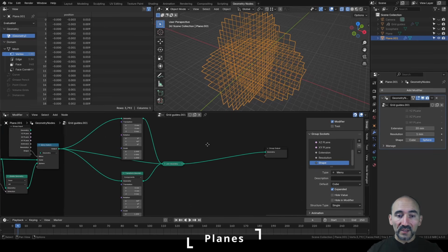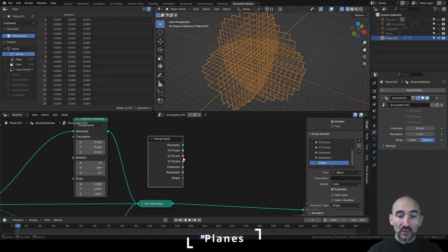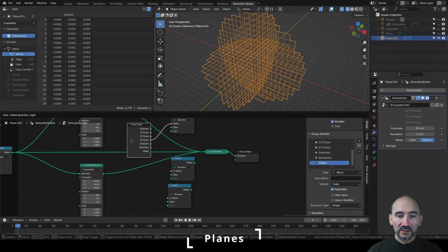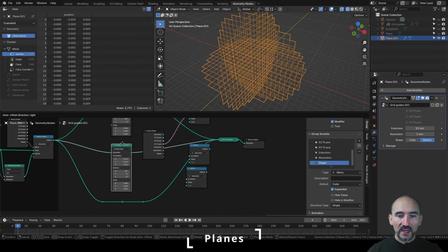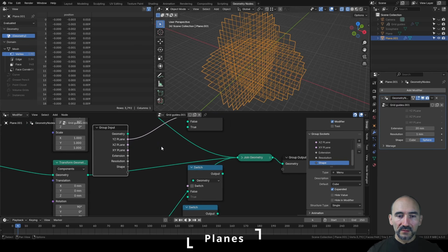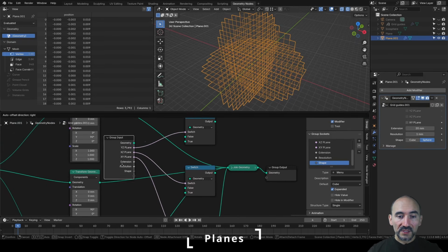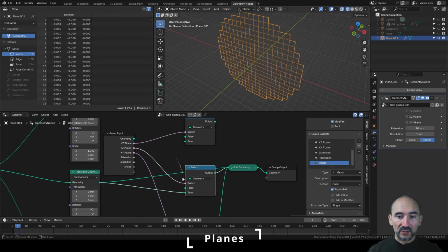But before joining these, we need some switches to enable or disable this viewing. So we can add the group input another time and ask if I want to see the X and Y plane in a switch, and we can duplicate this twice, move the join here, and we can make a reroute here and a reroute here and go down, because in this way I can easily link this here, this here, and this here. So if I want to have the X and Y, so the first plane we made, I can link these in the true, or otherwise we don't need any geometry and we can link this in the join geometry here. The same for this result, if we want it, and link here in the geometry and drop this line.